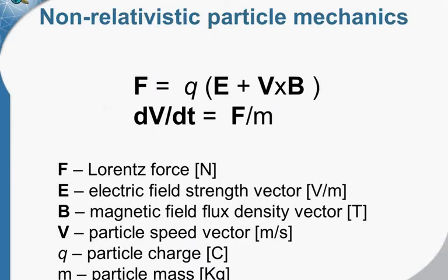This slide shows the set of equations which controls the behavior of a single charged particle in the non-relativistic case. Force and acceleration caused by external field in each point of the trajectory depend on the electric field stress and magnetic field flux density. Direct calculation of the non-relativistic charged particle trajectory is built in to QuickField Electrostatic Postprocessor only. However, it's rather simple to use the field calculated in other electromagnetic models and extract parameters needed for particle trajectory in magnetic or combined electrical and magnetic fields.